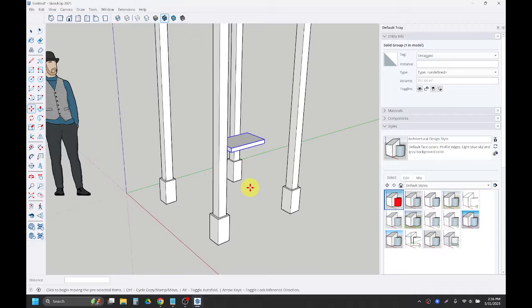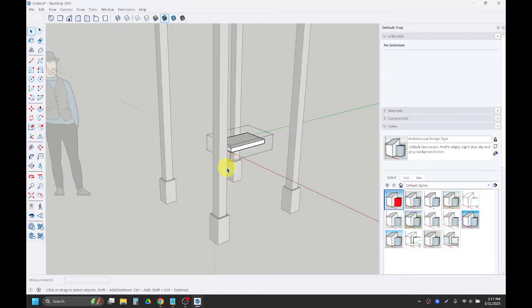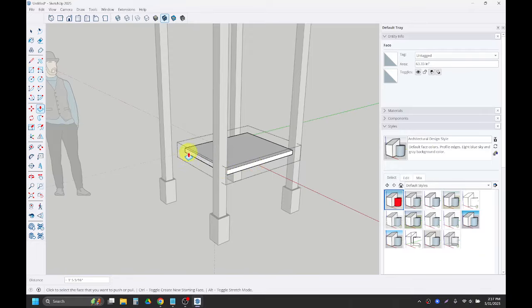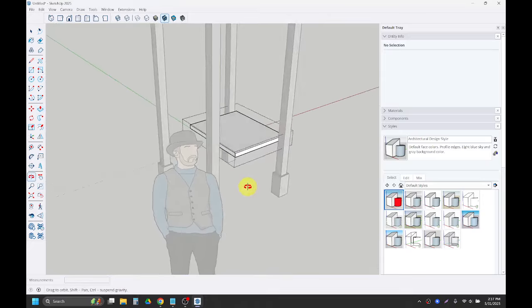Afterwards, I'm going to double click on it, and I'm going to use push-pull to pull these faces to these pillars in there. So I'll hit my space bar to get out of the move tool. I'm going to double click inside of the platform to edit it. And then I'm going to use push-pull, which is keyboard shortcut P, to click on the faces. And I can use some inferences to bring these edges to all of the faces of the pillars.